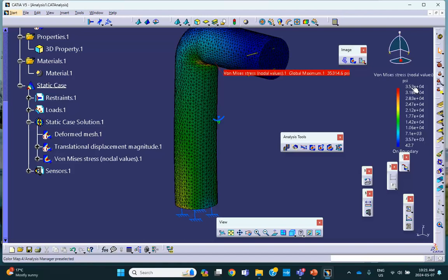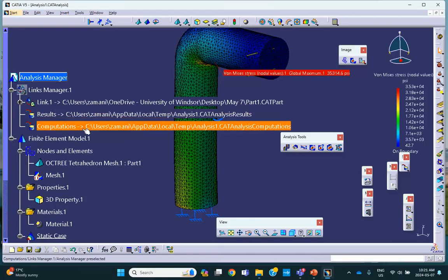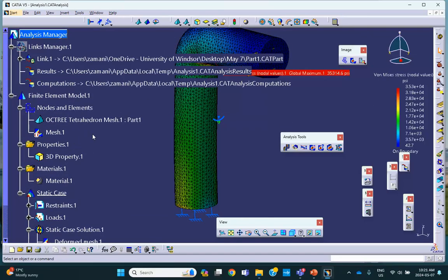So you see that 26,000? It's definitely better than linear, but it's nonsense, because when you made the mesh smaller, it showed you 35,000. Okay, yielding. So this is not trustable. 26,000 is not trustable. You have to make this thing smaller and see whether I can trust this number. So let's check it out. For example, that's what I mean by mesh sensitivity study.